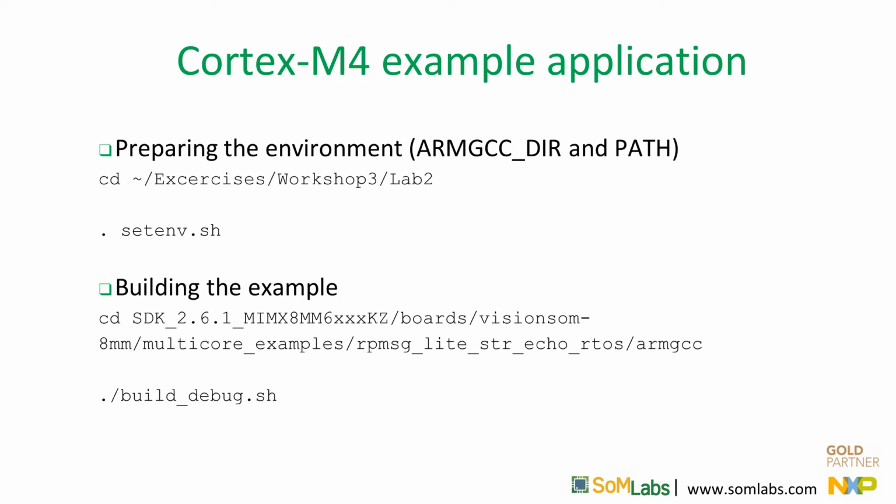We will use the build_debug script, which is in the ARMGCC directory, inside the directory with the example. So: boards, Vision SOM 8mm, multicore examples, rpmsg_lite_str_echo_rtos, armgcc.